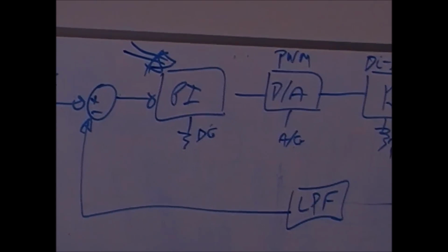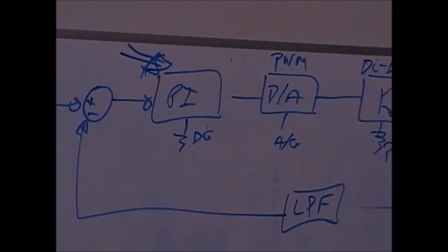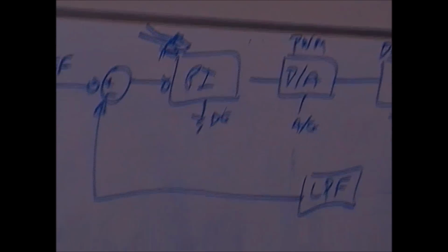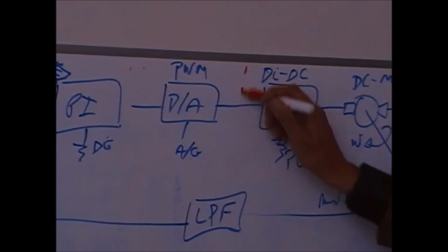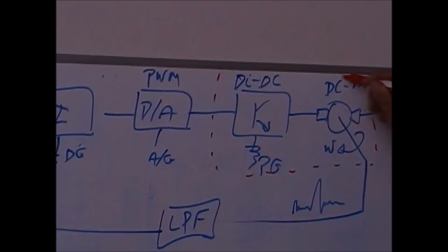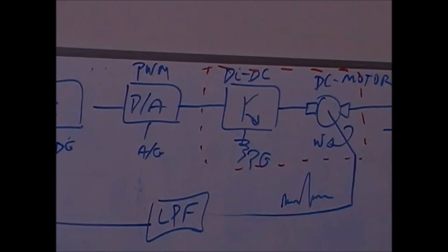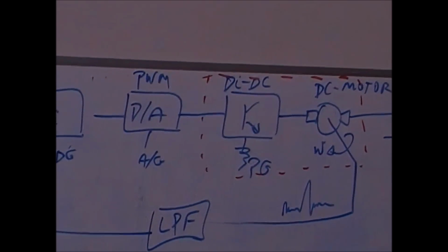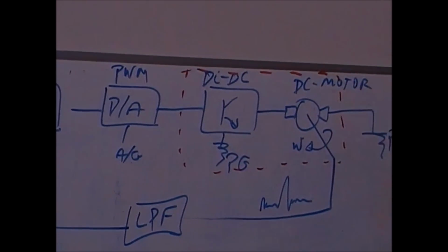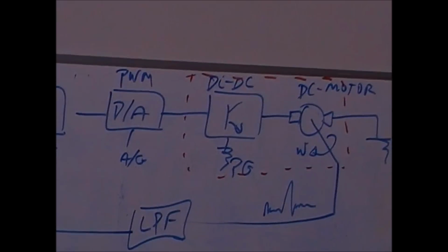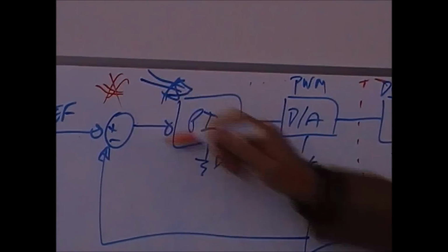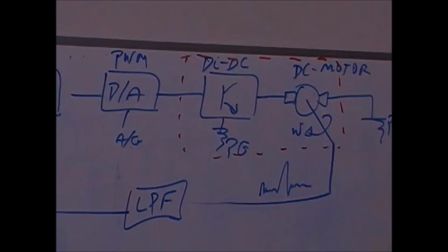One important piece of information: I need to know the gain and the poles and zeros for a system like this. That is the first step to be able to design. My objective is to design a PI controller, but first I need to understand what kind of system I'm going to control.